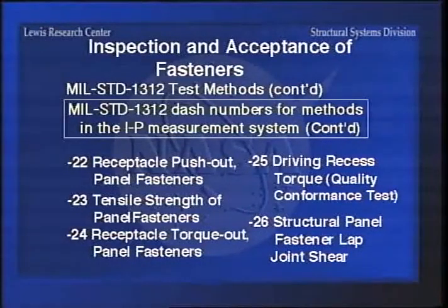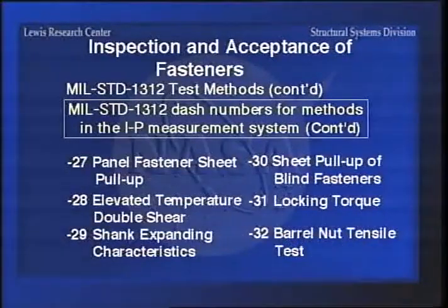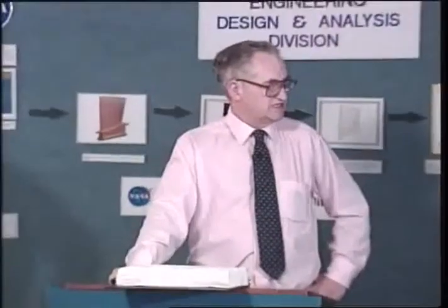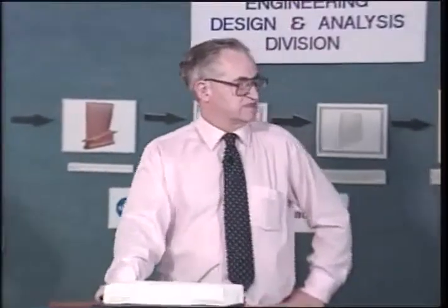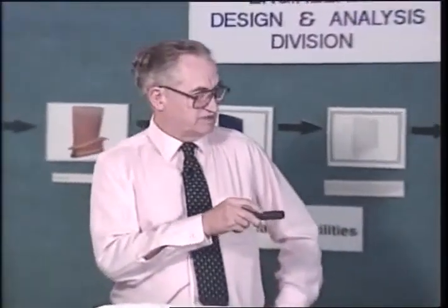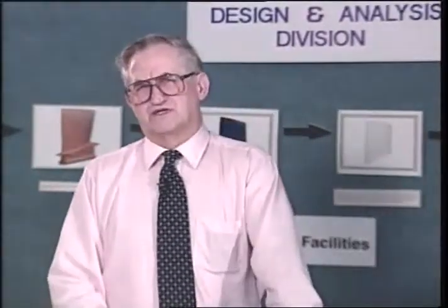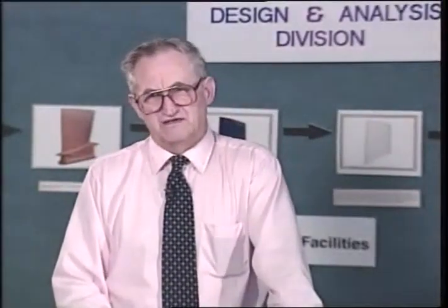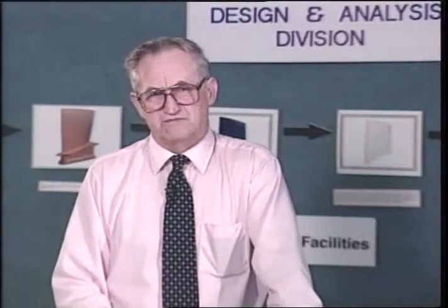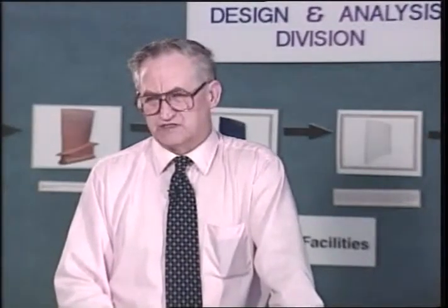Now this is something that is important, and some of the Cherry rivet type manufacturers, the pull stem type rivet manufacturers, have had trouble meeting this sheet pull-up, because if you have several sheets together, maybe they're not exactly flat, and you try to pull them up and clench the rivet.